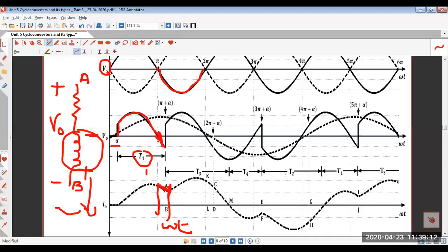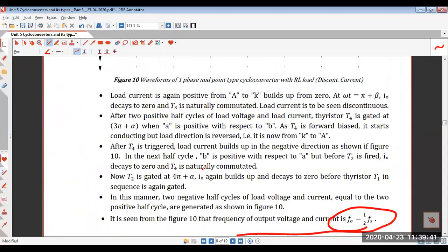Now this negative voltage will appear here for the duration for which your load current is dissipating during the negative half cycle when T1 is reverse biased. This will appear because of this nature, plus, minus and plus. So the voltage across this inductor would overcome the effect of the actual reference direction of plus and minus.